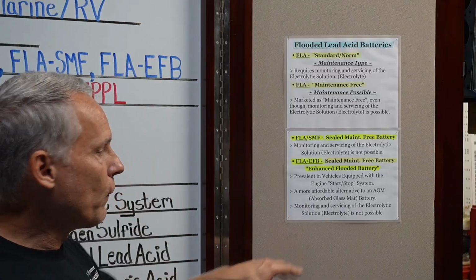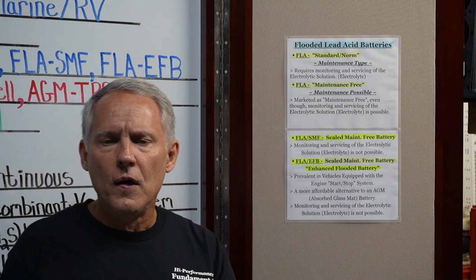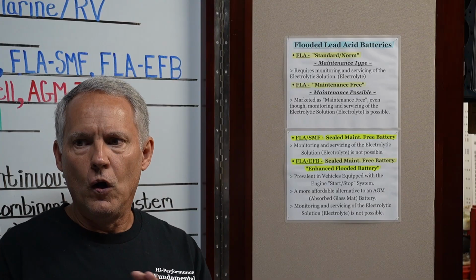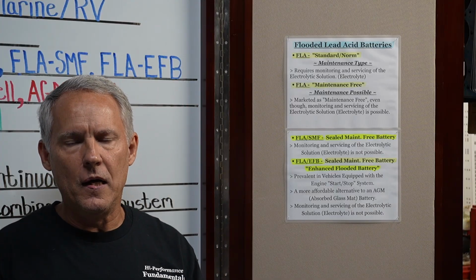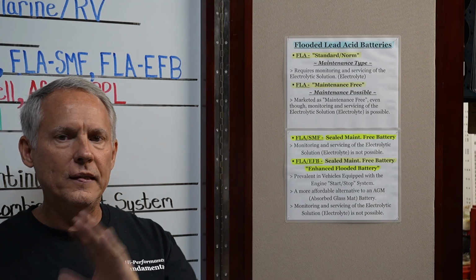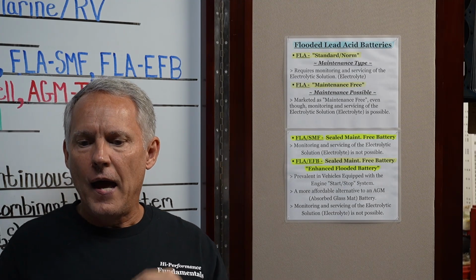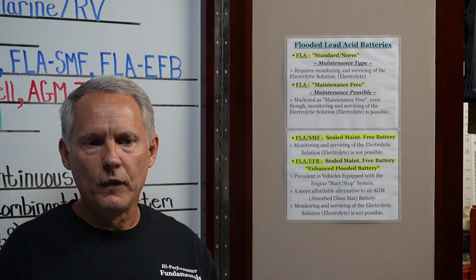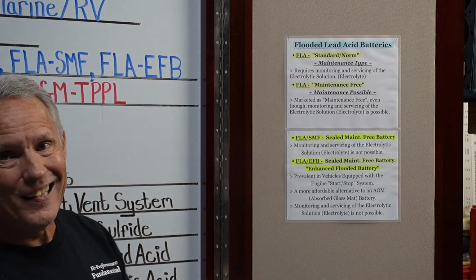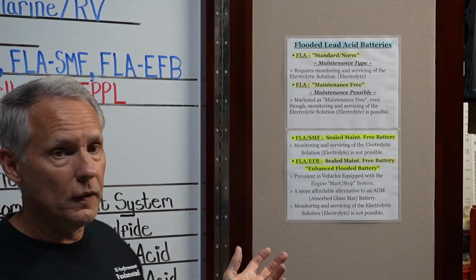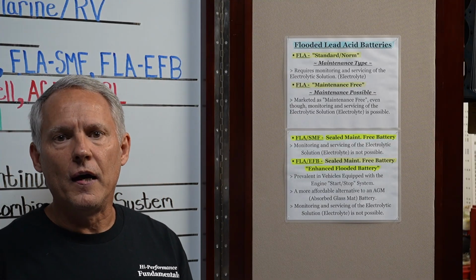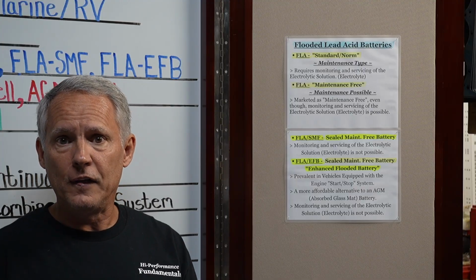All right. So from there, what I'm going to do is clear the board off. I'm going to go ahead and start comparing these batteries side by side to give you more of a technical idea as to what makes one different than another, better, or at least a better understanding as to why you would pick one over the other. And maybe you decide to go with the standard norm FLA maintenance type battery, and maybe you decide to go with the very top of the line, most expensive AGM battery you can find. At least you have an understanding as to what you need to know to make that decision.